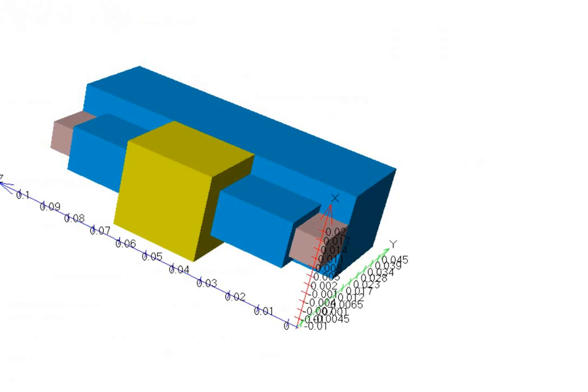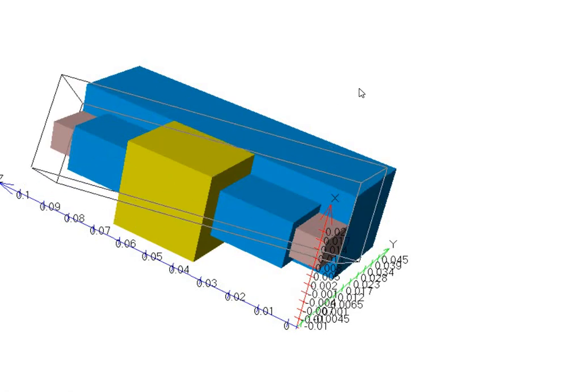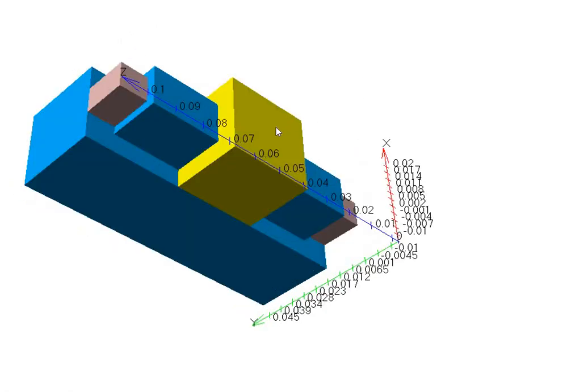This is the structure file. I have defined the work area, x direction 0 to 0.02 and z direction from 0 to 0.1. Y direction is minus 0.01 to 0.02 and the x direction is 0 to 0.04. I have defined everything in the work area. This is the structure file. By using the cut plane, you can find out the potential energy band diagram from the structure file.